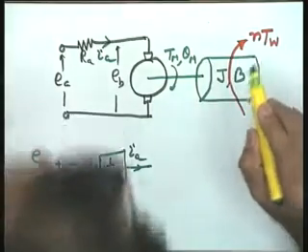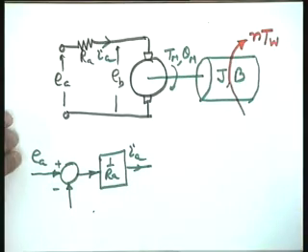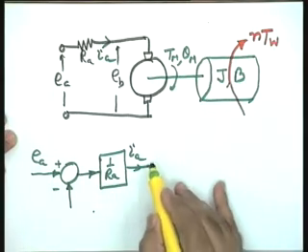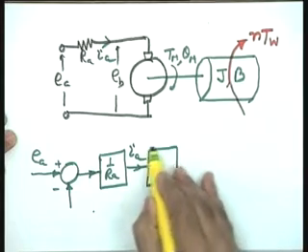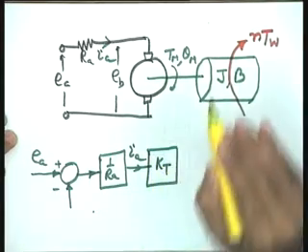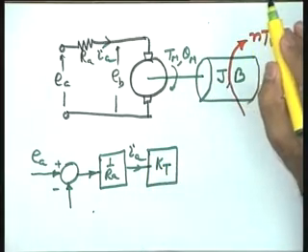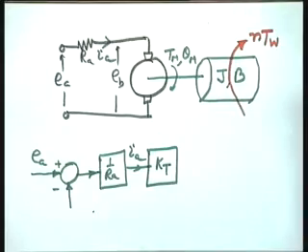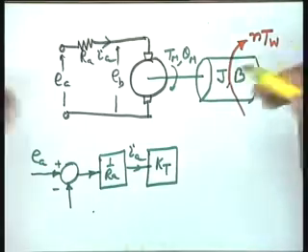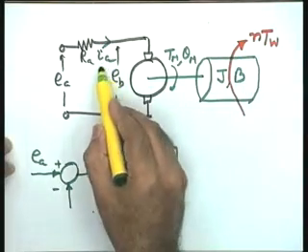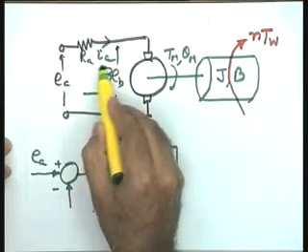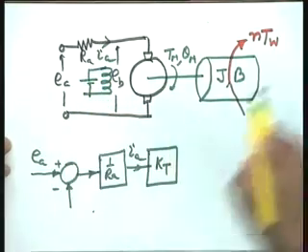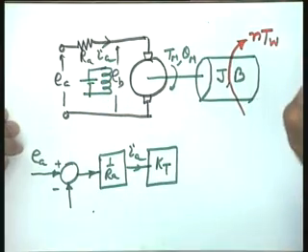Now, this action plan is coming directly through a block diagram. This may please be noted. This is armature current, and if I multiply it by a torque constant kT, you recall your torque is proportional to the product of armature current and field current. So, in this case what I am doing is I am taking the field constant. Okay. You will note this point please here.